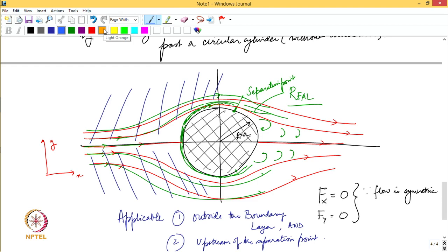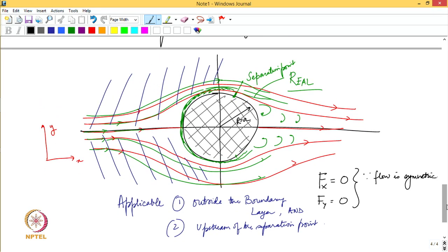So, conventionally the way the earlier CFD solvers used to work was that they used to calculate flow outside the boundary layer using the same approach, that they would solve using a potential flow solution, which is what we are doing. We are solving for potential flows, irrotational flows. They would then stitch the solution or marry it to the solution computed from within the boundary layer.